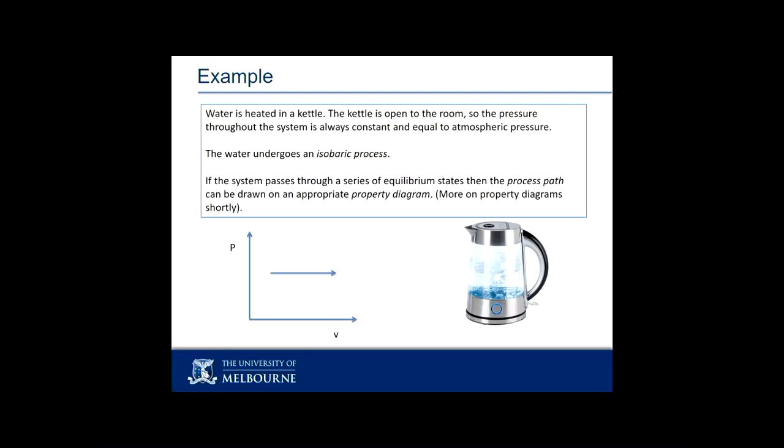How do I know my specific volume is going up or down when I boil the water? So I'm boiling the water, and what's happening to the level of water? It's getting lower and lower. So how could I say that my specific volume is increasing? Because you divide it by the mass. Okay. That's one of the key things: I divide by the mass. There's another important thing, which is when I look at the water level, all I'm looking at is the liquid water.